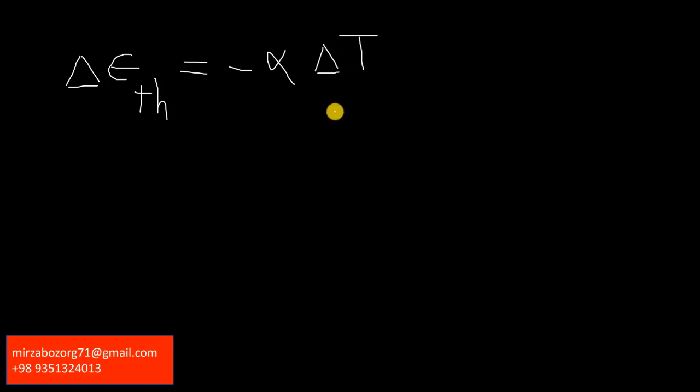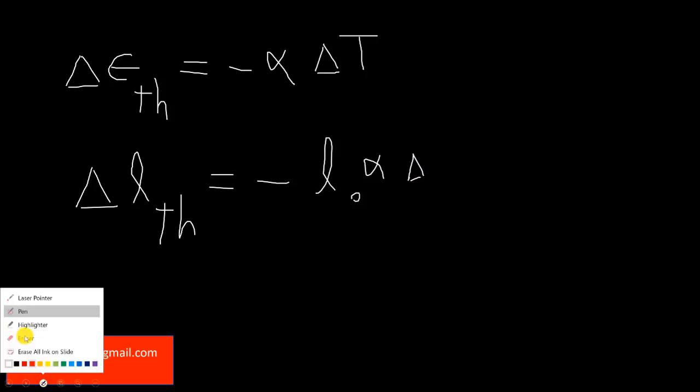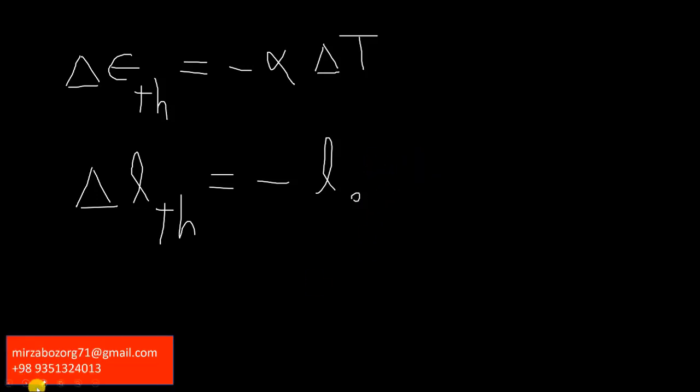Okay, and because when the temperature is increasing, thermal strain causes compression, this minus is because of that. And delta L thermal is equal to minus L0 alpha delta theta, delta T or delta theta. Both of them are correct.